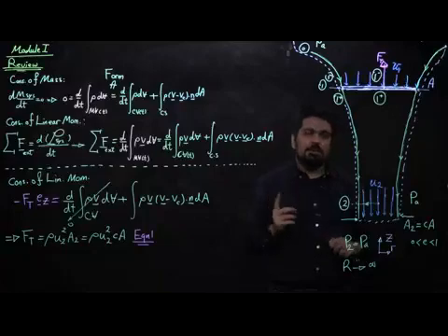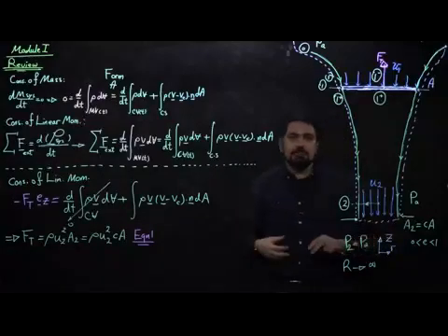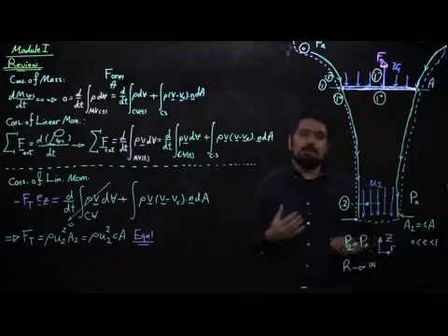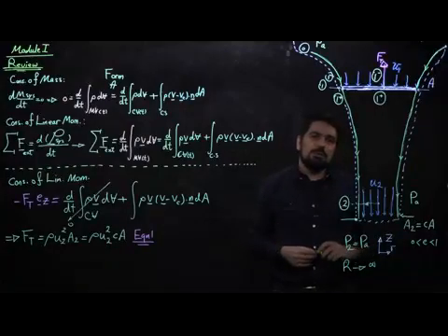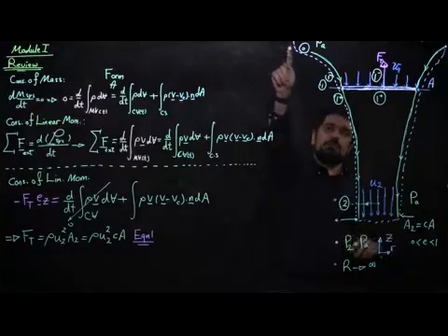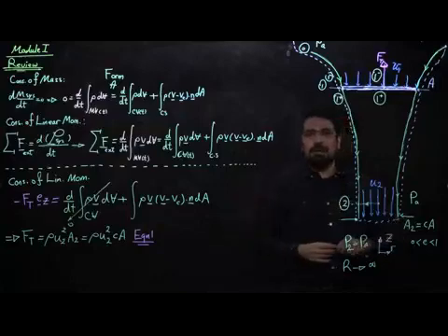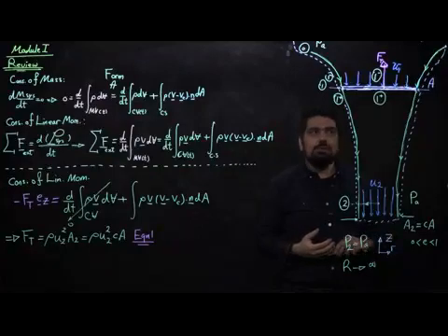So we always need to think about it very carefully, that Bernoulli is conservation of energy. But if the system goes through a shaft or goes through a blade and gets some external energy taken or given to it, we cannot really use Bernoulli equation anymore. But any position before the blade and after the blade feels nothing other than an inviscid flow that has no exchange of energy with the outside world.